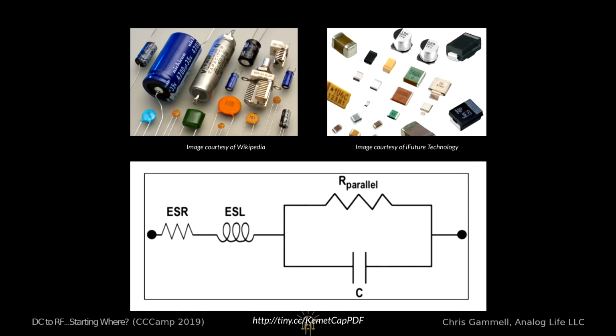And again, we've already talked about this. Those are inductors, effectively. The same thing happens, though, at low frequency. You can never really get rid of that inductor. And what we have below there is the equivalent series inductance, the equivalent series resistance, parallel resistance, and then the actual capacitance itself. This is kind of a bulked model of what a capacitor is. And what happens is, as you start to move up in frequency, you start to see effects that you wouldn't have seen at lower frequencies.